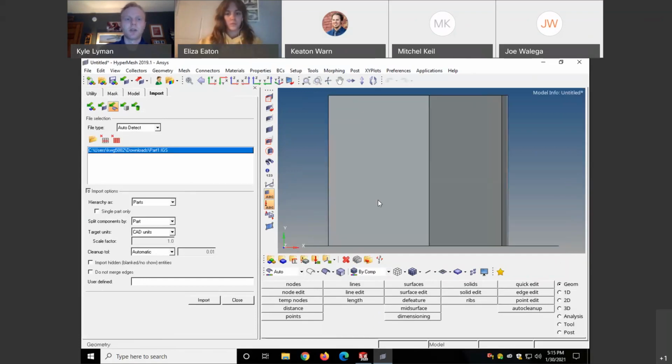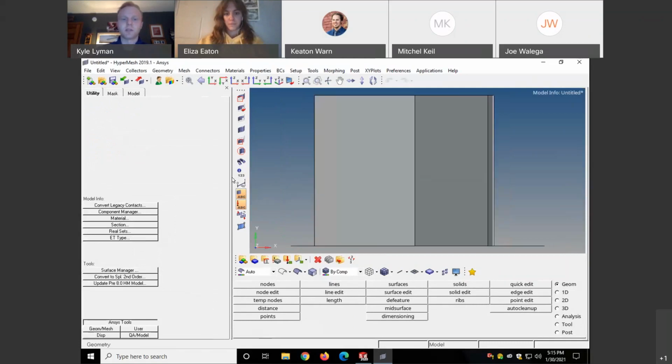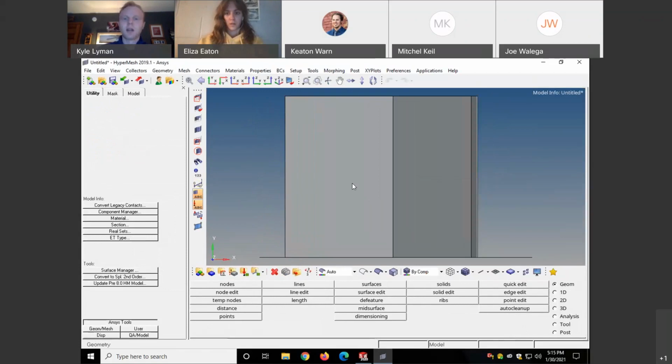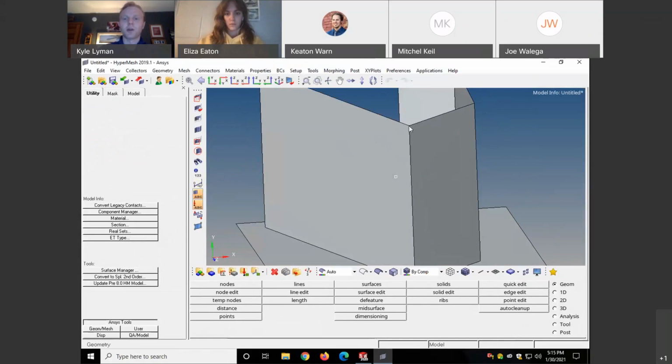And there's our file. So I'm gonna hit close and move this just a little bit, just so I have some more screen space. That should be fine. Okay. Now, to control this, I know you can't see what I'm doing with my keyboard, but you have to hit the control key and hold it down, and then left click to rotate. And you set your rotation point by a quick single left click.